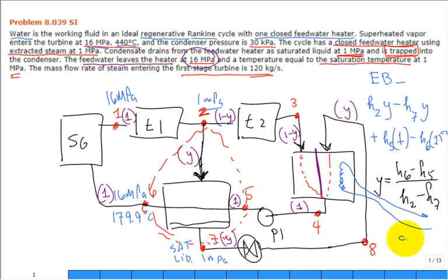That's called the cooling water. It's lake water, river water, ocean water. Okay, that water experiences a temperature increase when it goes through there. And in this problem, the temperature increase is 18 degrees C, isn't it? So maybe it comes in at 20 degrees C. What does it go out at if there's an 18 degrees C temperature increase? 38.